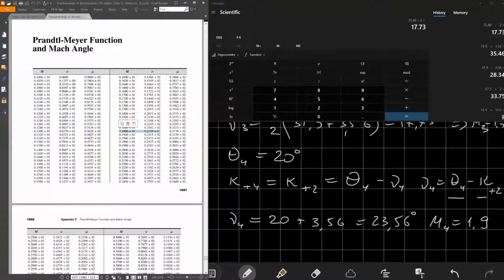We just need one equation, right? And we use a predefined value of the wall direction. Or if we are calculating on the axis, we are using theta equal to 0. And this is how we find out the value of Mach number on the wall using method of characteristics.